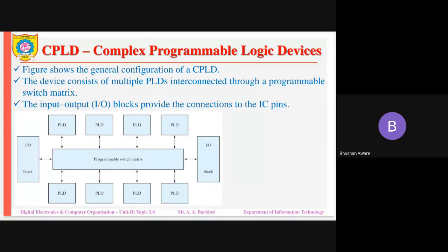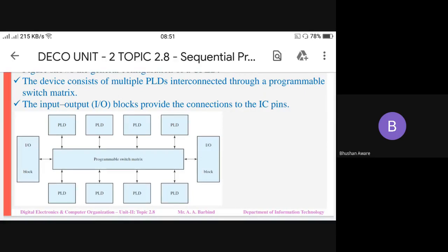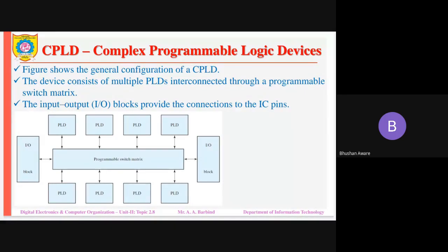So what is programmable in all these devices? In all these programmable logic devices, it is the making of some connection or no connection. Based on that, if you make some connection, the functionality will be something. If you break some connection or do not make that connection, the functionality will be different. It is not only one connection, but there are a large number of such connections at every cross point, and because of that the functionality of the devices will change.